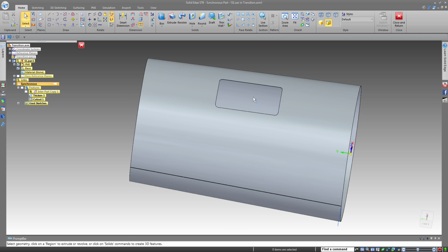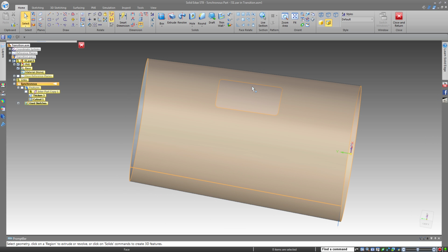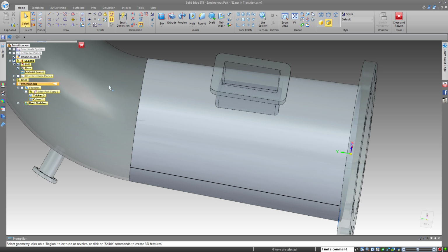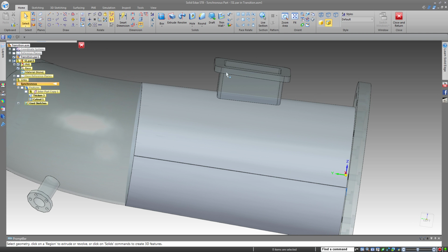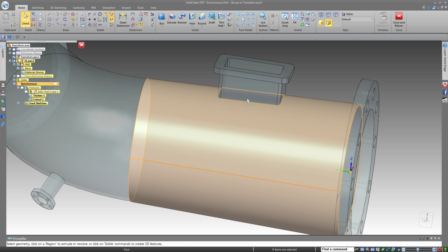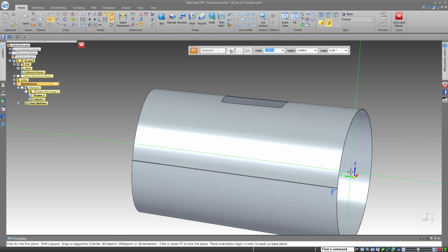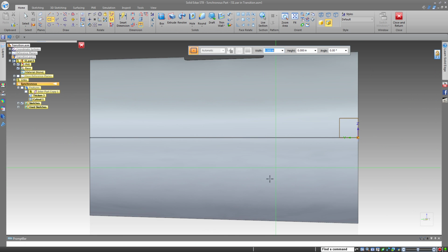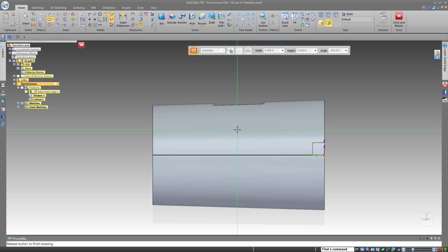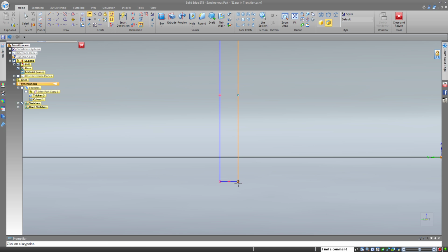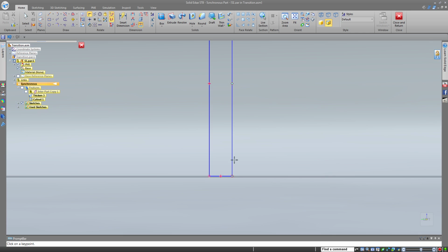Of course, if it has a flange on top of it, which I believe it does, you can't just slide that over the top of it, and you don't want too big a gap around it. So in most places they would have a seam along here, which they can just wrap around it. So we'll go ahead and do that as well. I'm going to do another cut on this plane. We'll just make the seam straight up and down, even though it is at an angle. So I'll apply some geometry here.